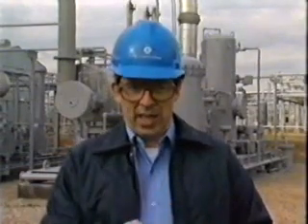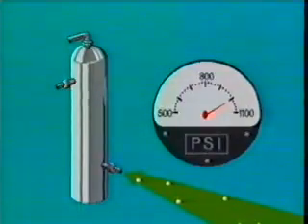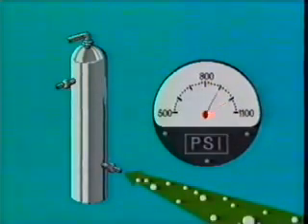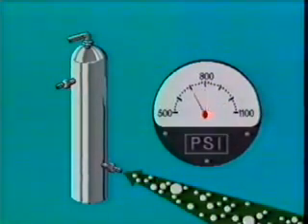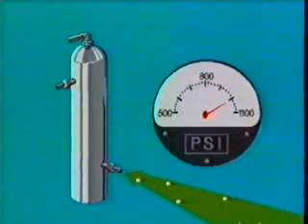Now, low inlet gas temperatures increase the tendency of glycol foaming. As you will see later, foaming creates significant operating problems. Now, in the normal operating range of a glycol dehydration unit, inlet gas pressure is not a critical factor. However, at constant temperature, gas can hold more water as the pressure is reduced. Therefore, operating the unit with a higher inlet gas pressure will lower the water content of the gas.